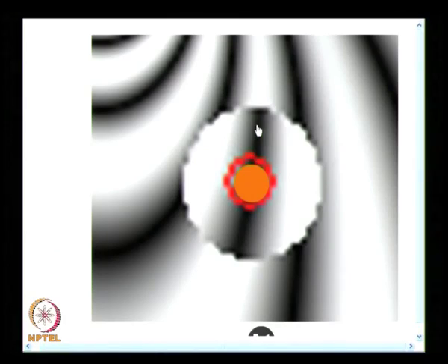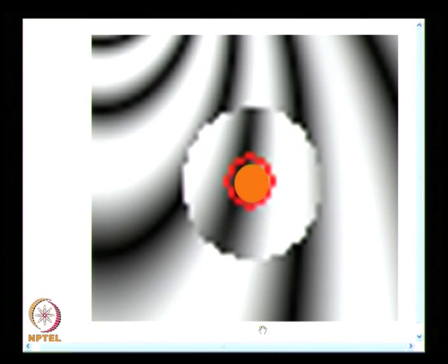That is the way the calibration is slightly done differently, but the physics is same. You have to know in all compensation techniques whether a higher fringe order has moved and come to the point of interest, or a lower fringe order has moved to the point of interest. And in this case, the animation clearly shows a higher fringe order has moved to this point of interest.